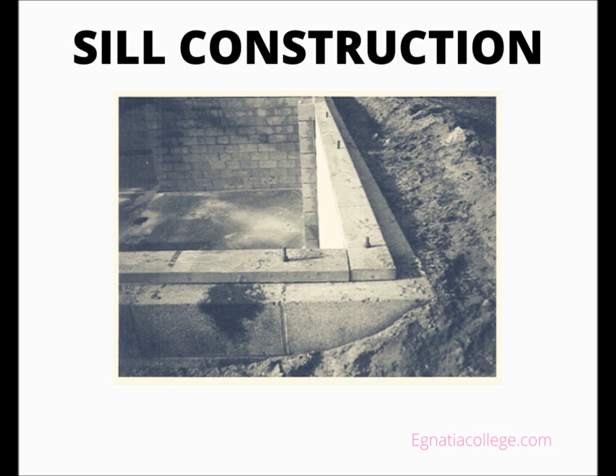All lumber in contact with the foundation, including the sill plate, must be pressure treated, PT, with an approved chemical to prevent decay.